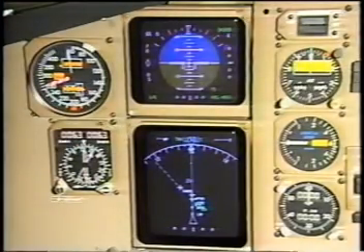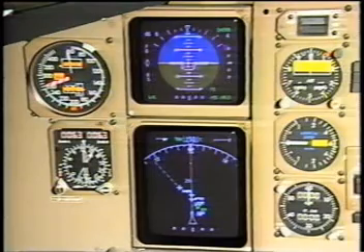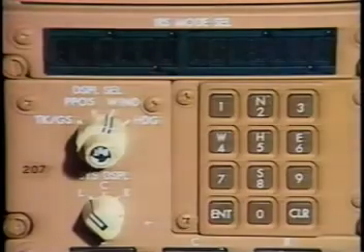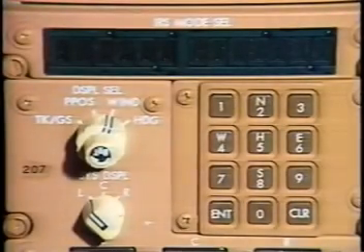If the IRU is in the nav mode and receives an invalid airspeed input from the ADC, or a true airspeed less than 100 knots, the IRU outputs wind speed and direction as no computed data. The result is a blank wind display on the EHSI and the ERMP numeric display.